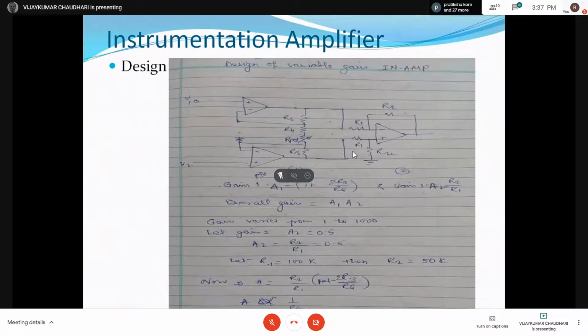Okay, initial circuit we have taken this is R4 and this is R3. So I am taking R2, R1, R2, R1, R2 here because anyway they are considered to be equal, right? So here instead of R5 and R6, I have taken R3 and R3 only because they are to be equal and generally they are in the design. Okay, so R3 and R3 and RG is replaced now by fixed resistor R4 and a variable potentiometer. Okay, and as usual, this is one amplifier, this is another amplifier, and this one is the next stage amplifier. So this here is V1 and V2 instead of VA and VB.